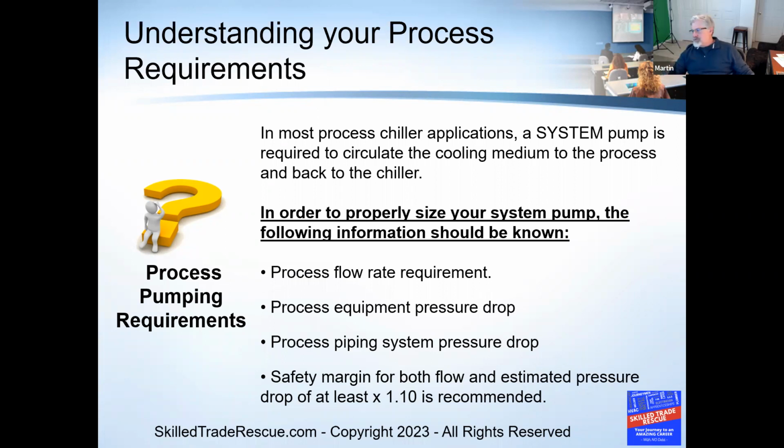And the second compressor was never running, no matter what they did, right? So after we peeled away the layers, we found out that we have their safety factor plus our safety factor. We were selling them a chiller that was massively oversized. So sometimes that can get you into trouble, and a lot of times you don't know about it. But I always argue, if you're going to be running into a sizing problem, it's better to be too big than too small. And then we're going to also get into the different plumbing systems, and I'll tell you why on one type of plumbing system we call a research system, you can get away with that, right?